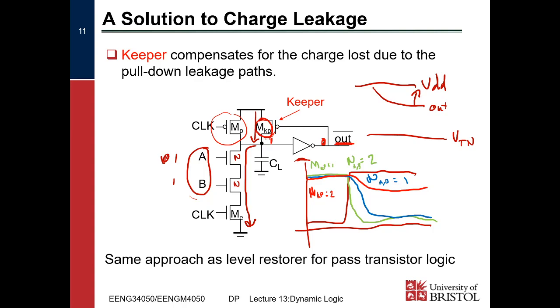We also saw this with the design of the sequential section. We saw that, with the bistable circuit, we need to overpower that feedback loop between the two cross-coupled inverters, right? So either we cut it or we just overpower it, right? With our sequential logic, right? The point here is that the bits that need to overwrite it must be more powerful than the bit that's holding it there, right? And that's what this graph over here was.